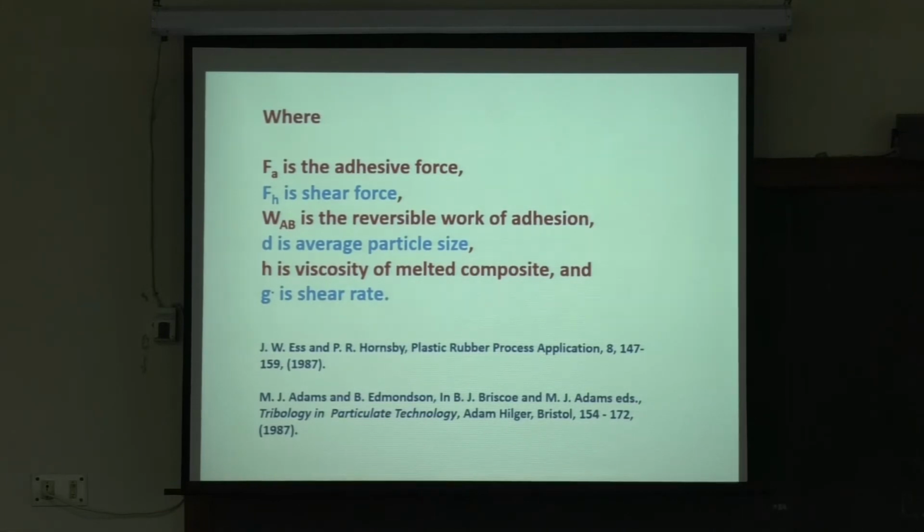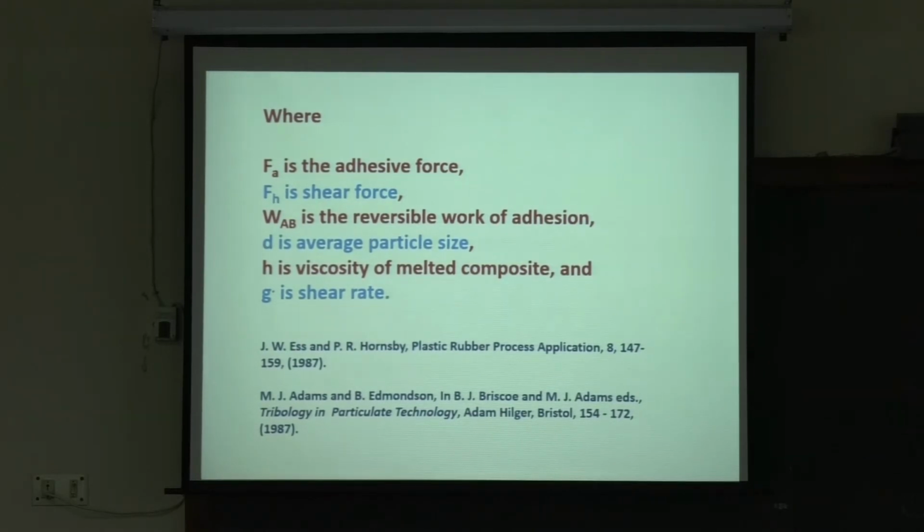Shear means, if you're pulling something, it's tensile. If you're pushing, it's compressive. But shear happens all the time, because there is stress transfer even when you're doing tensile tests. Often the shear is happening along 45 degrees, particularly if you have a ductile material. The shear is always there, so that component cannot be neglected.